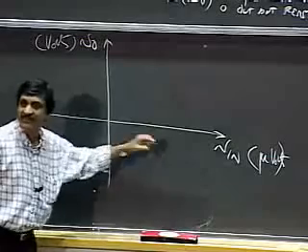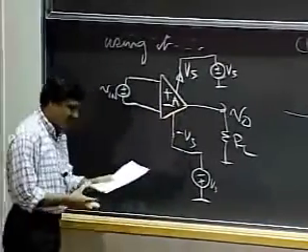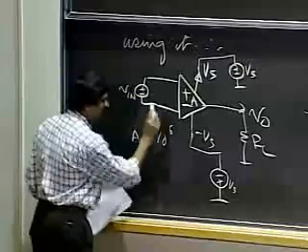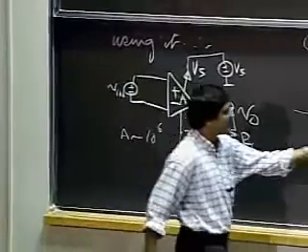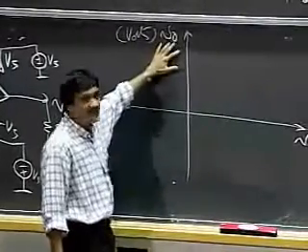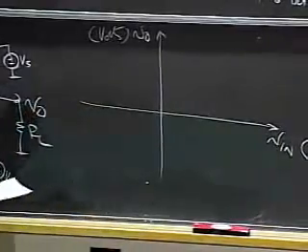Okay, V in is going to have a very, very small scale, in microvolts, because remember, the gain of this is huge. Okay, it's on the order of 10 to the 6. It's huge. So small changes in V in are going to cause massive changes in VO. Okay, so I have a very fine scale on the x-axis.